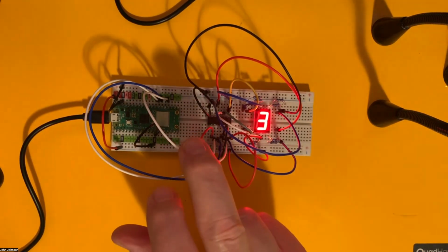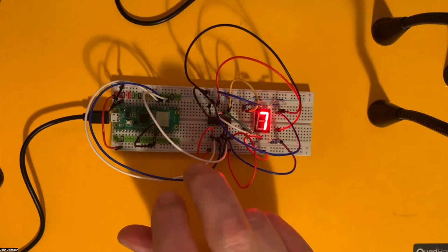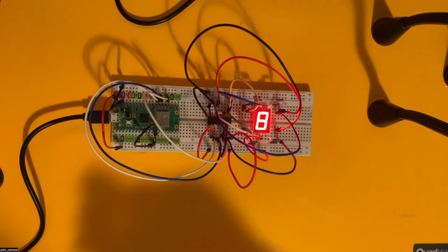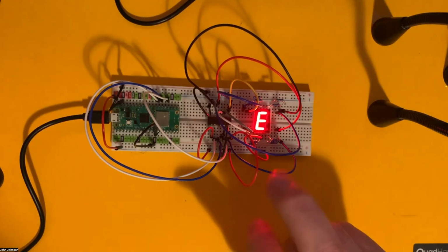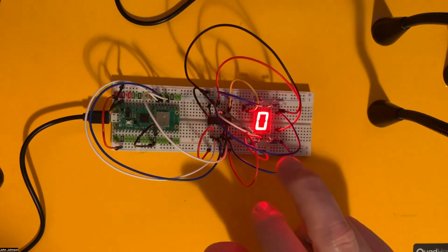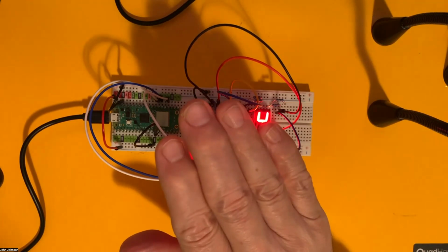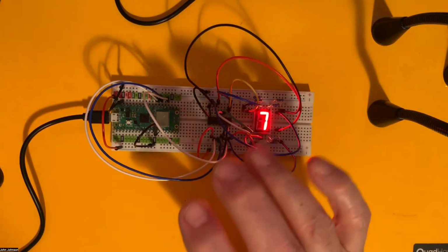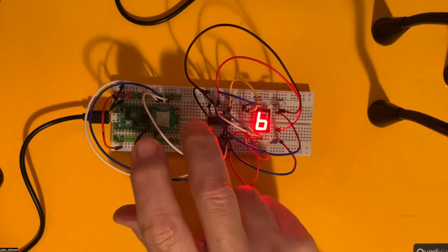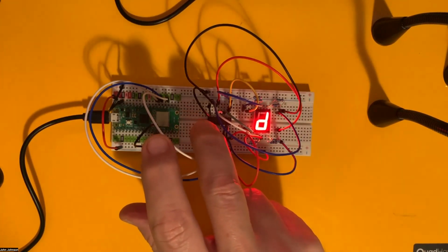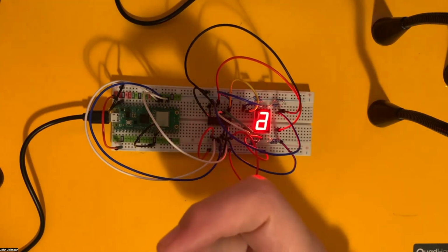I thought maybe we had some crosstalk on our wires, or some other problems. I went over and checked every single wire two or three times to make sure everything went to the right place, and it just made no sense. I could push my wires a little bit this way and it would come out differently. What it turned out to be really was the IC chip. When I pulled it off and looked at it, I could see that one of my pins was bent under.